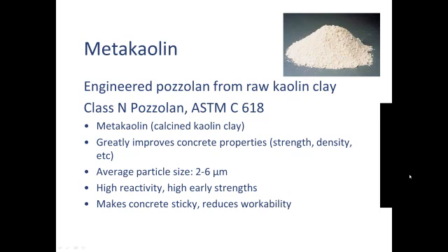Probably the one reason why it fell out of favor is because it's engineered from raw materials. It's technically not green. Or not as green, let's say, although it's a very fuzzy topic I'm not going to jump into. And it tends to make the concrete sticky and reduce your workability, which is actually useful for some things, because it can act like a viscosity modifier in your mix.